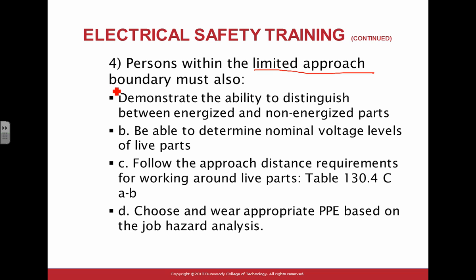So limited approach boundary. You are in limited approach boundary. If you are to go there, you have to demonstrate the ability to distinguish, to tell that this piece of equipment is hot and this is not. So can you verify? You look at a receptacle like this one. This is supposed to be the hot, this is supposed to be the neutral, this is the ground. When I say supposed to be, that's how we should wire them. But always verify, because you never know how it was wired.